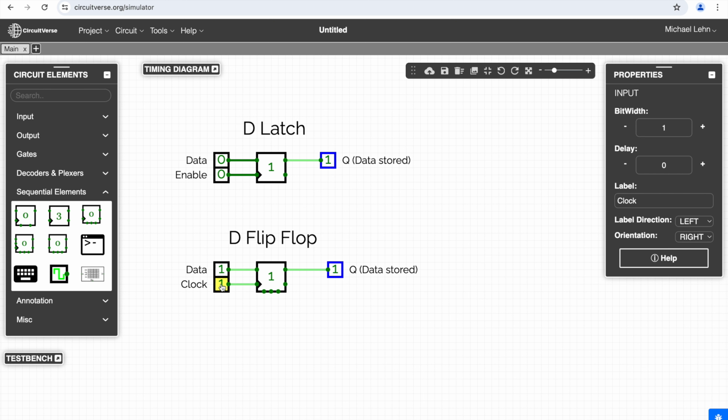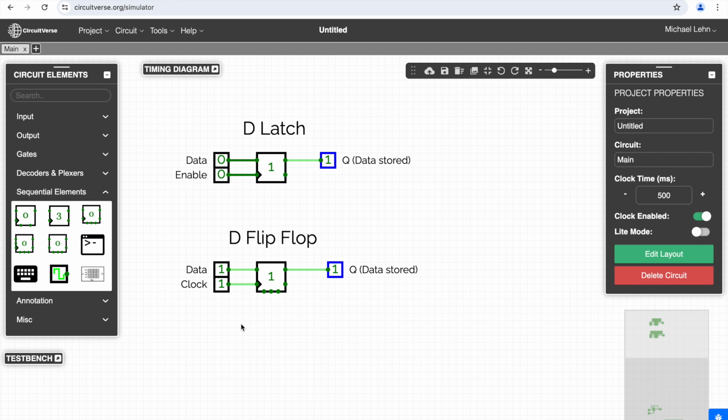So let's switch the clock back to 0 and change data to 0. Then it becomes clearer what I mean. If I now change the clock from 0 to 1, when I generate a rising edge of the clock signal, I again have this information flow, that data gets copied into the D-flip-flop. And then I again could change data back and forth, nothing happens. Nothing happens until the clock again goes from 0 to 1. Okay, so that's what we already experienced in the exercises.